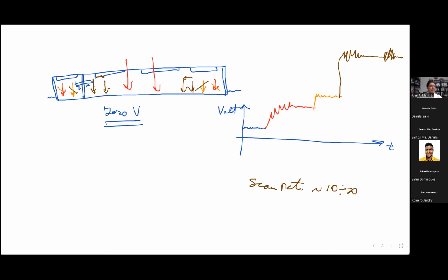10 kilograms, I believe. 8 kilograms. So we have a capacity because we have two load cells in parallel, so we can support up to 20 kilograms. But the problem is that they are joined to covers of wood, and we could have some deformation. So that's why I would like to start with 1 kilogram for W1 and W4. Then we can go on and see if we can increase this value.